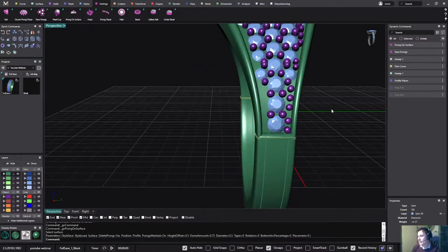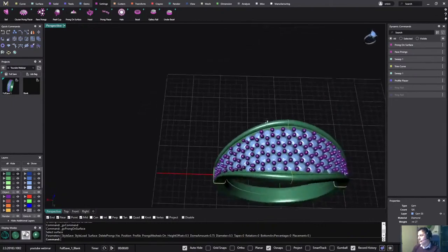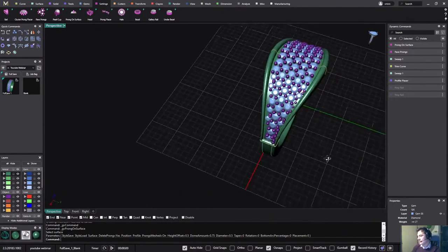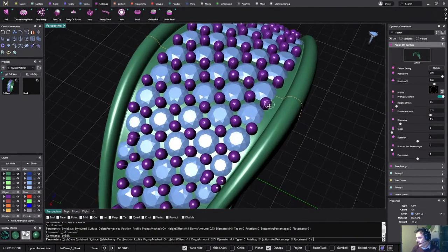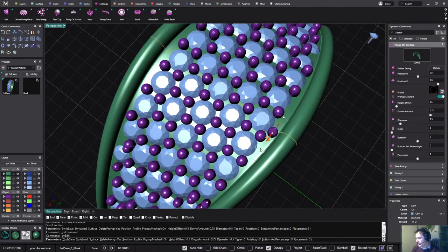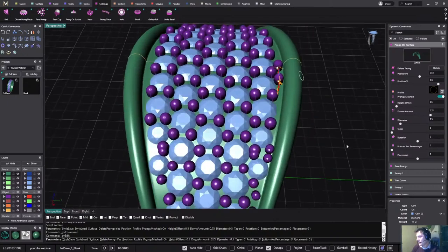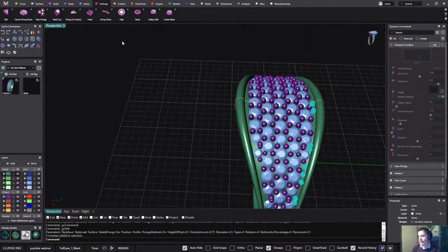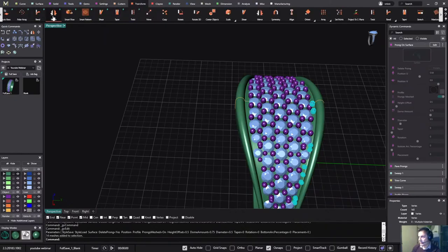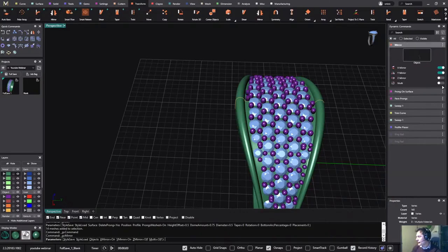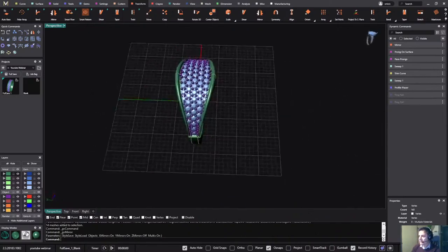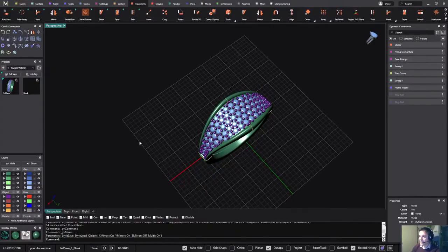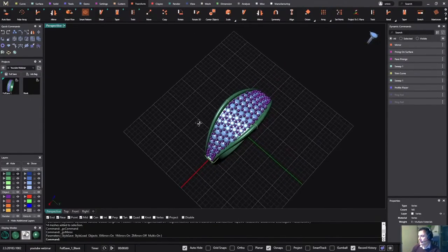Now, from the moment that I have all this, you see I'm missing the prongs in this side and in this side. I missed a few here, but I can just go back, edit, and keep adding them, because the software is parametric and you can go back to the tool. Okay, and now the only thing that I need to do is just select, and from transform I can go and use the mirror, and I use the mirror to the 4 sides, and there we go. We already get the ring with all the prongs and everything that we need.